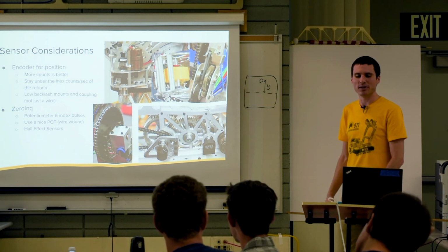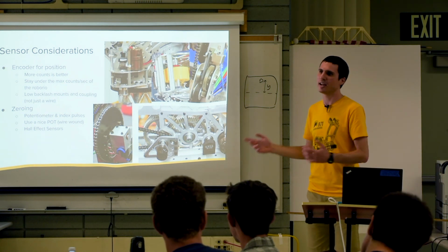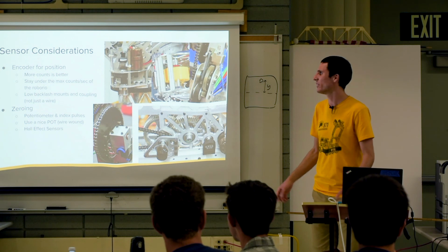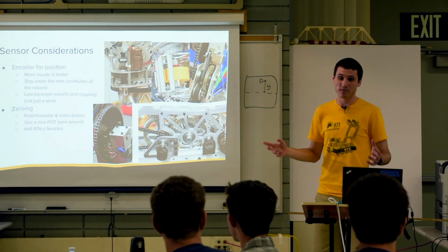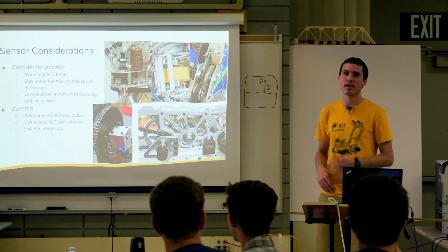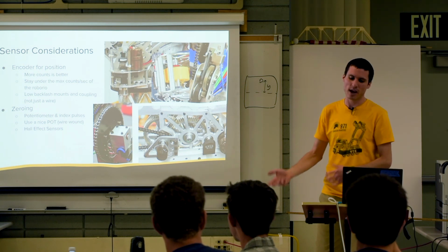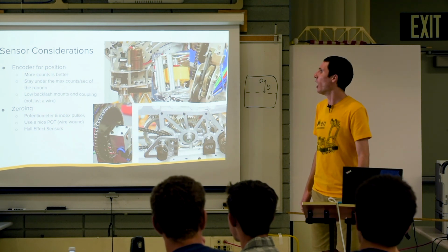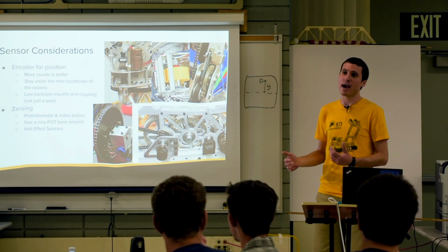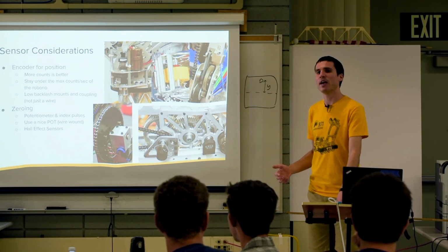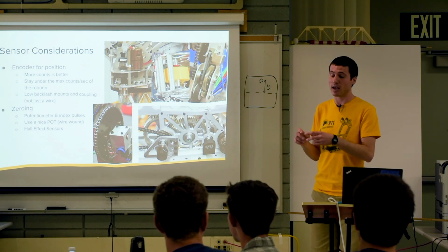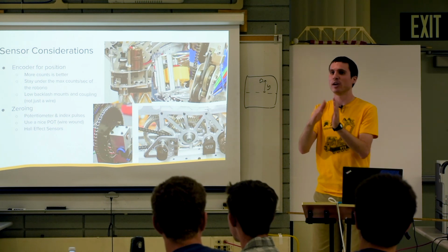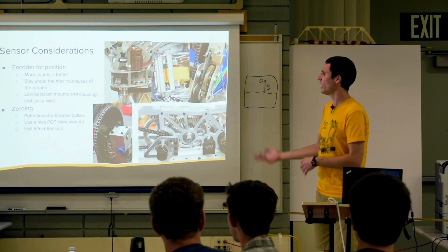And then, we're building the systems to be controllable so that we can have control loops on them. It's important to keep track of where you put your sensors and what sensors you put on. So the people doing the controls and the software should be driving what sensors they want. So work with them on that. But basically, you have two problems. You want to be able to tell where the mechanism is within its range of motion, and you want to be able to know how far it's moved, as sort of relative position. So that's relative position and absolute position.